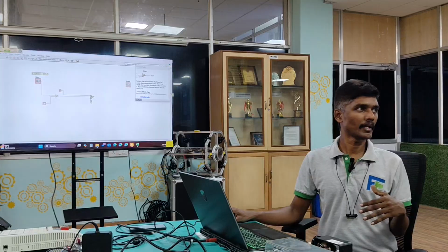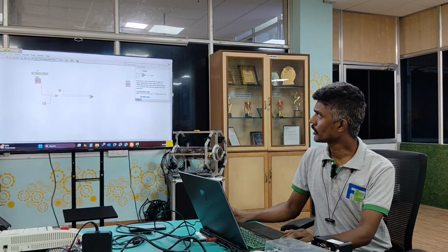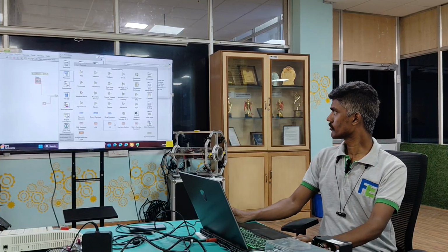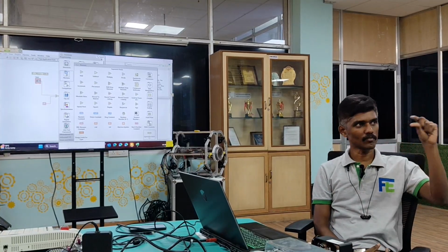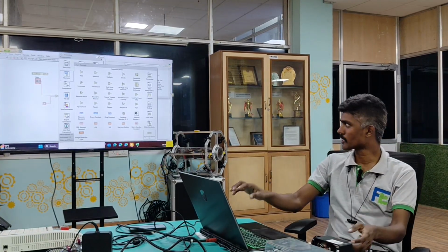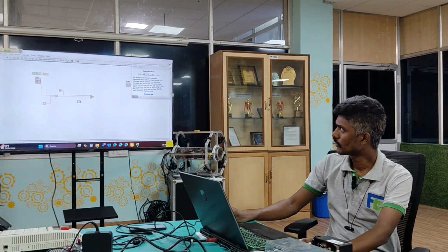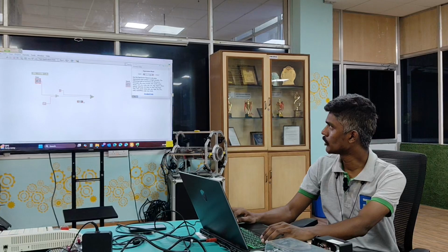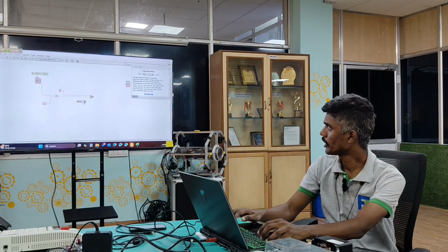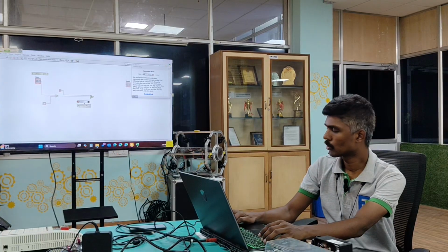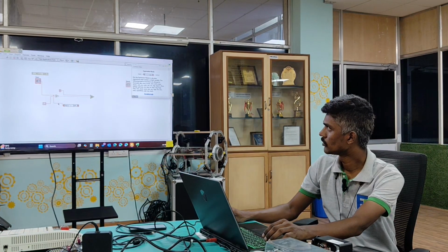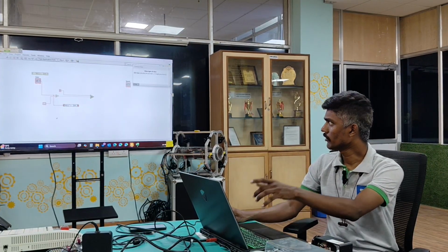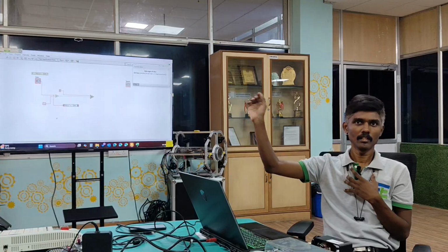If it is greater than 1.2, you need to have one equation. So this is your equation. For that, go to numeric, and there is an option called expression node. If your equation has only one variable, like only one variable x is present, you can use expression node. Place it here: 1922.2 multiplied by x minus 2241.7. Give your gain as an input and provide your equation.